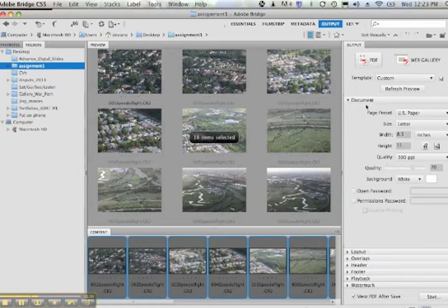It has a couple of drop-down menus that we need to set. There is a PDF handout in the assignment sheet of how to do this. So if you're confused, just reference that, and it gives you step-by-step directions. It's the same method that I'm using in the tutorial, it's just printed, and you'll find that back in the lesson. So over here, our document is US paper and letter, that's correct. Our quality is 300 ppi, which we now know is appropriate for printing, so we're going to leave that. So this is good, US paper, 300 ppi.